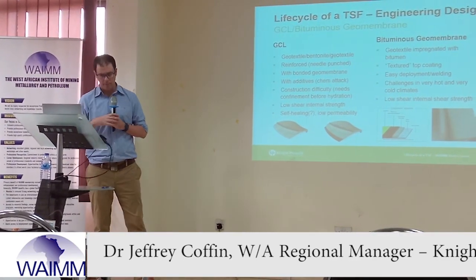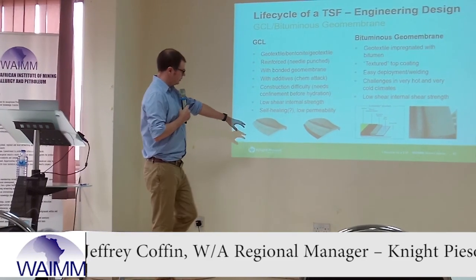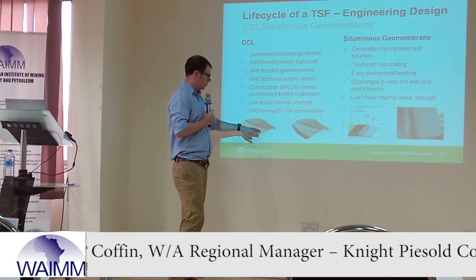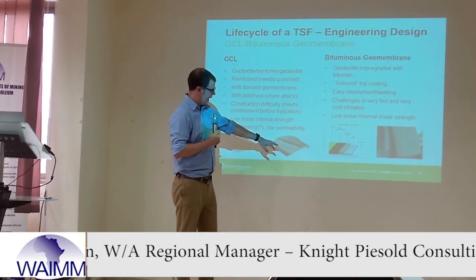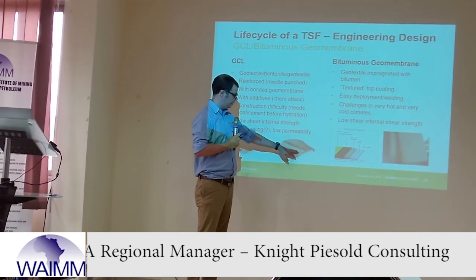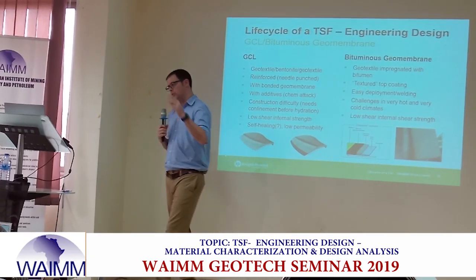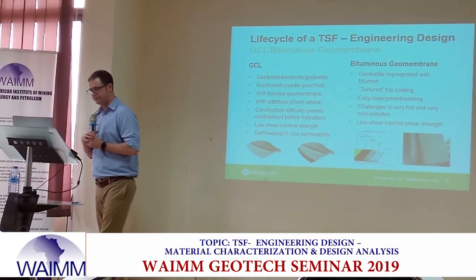GCL, bituminous geomembrane, again, this is just an interaction. Here's our fabric with bentonite in between it. Now you can actually buy these that have fabric, bentonite, and a geomembrane, so you have a composite system in one.